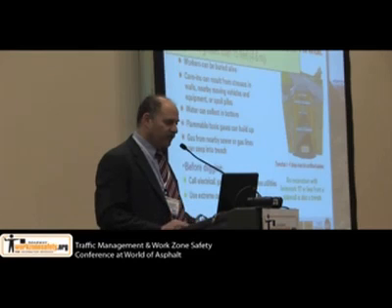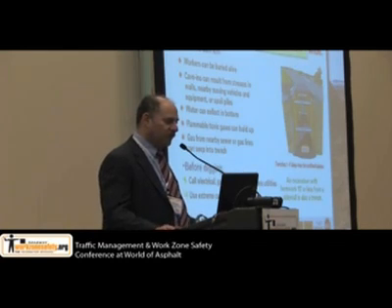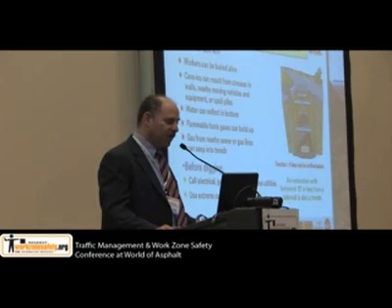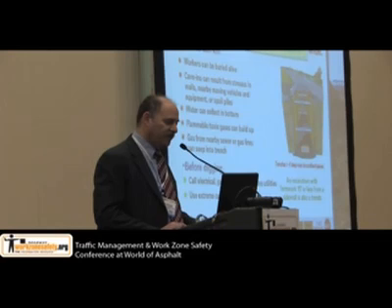It defines what a trench is. And here are some of the rules on calling before digging. The estimated location of the utility that may be expected to be encountered during excavation shall be determined prior to opening an excavation.